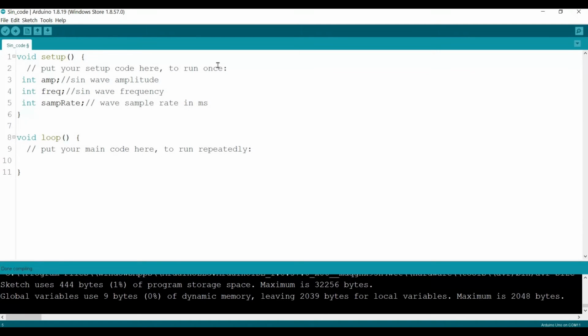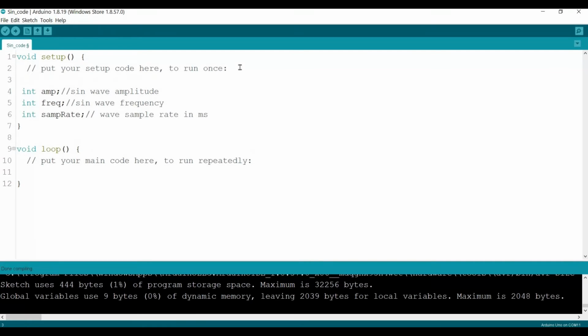And for sure we need to declare on the top. We need to declare the serial and initiate it. Again, the baud rate we just go with the default one, 9600. Baud rate, bits per second. Okay, let's go to the loop function.